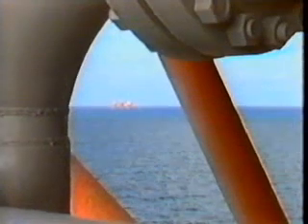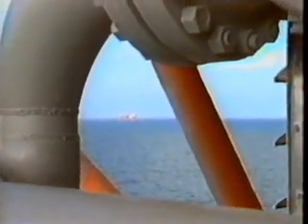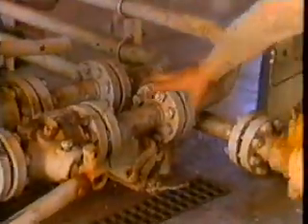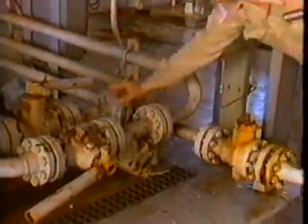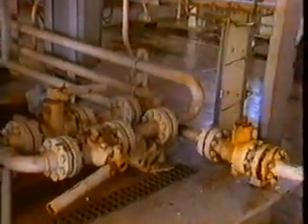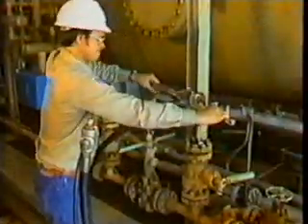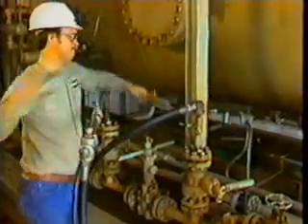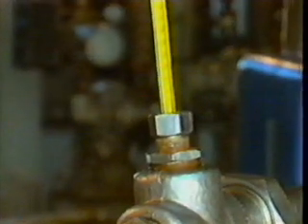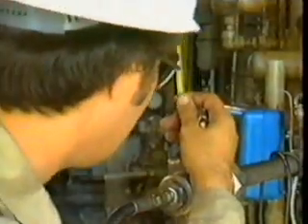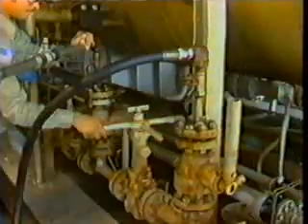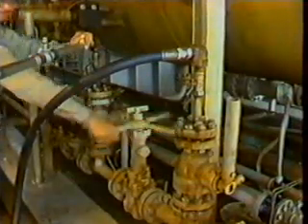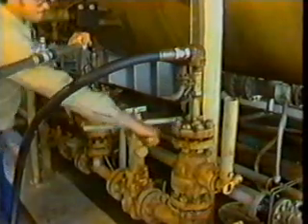Master meters are desirable where space or remoteness prohibit the use of standard pipe provers. To prove a meter using a master meter, you need to make sure that there is a working strainer upstream of the master meter, and then connect the master meter. Record the operating flow rate, temperature, and pressure of the flow meter. Now direct the flow of the meter being proved into the master meter.